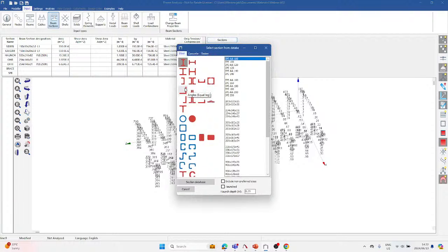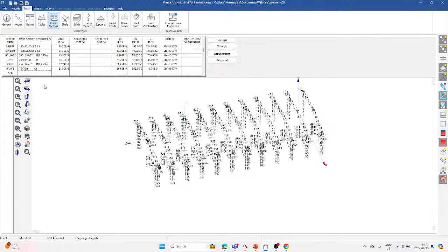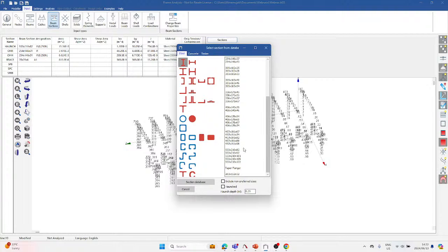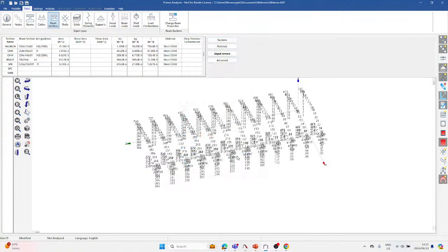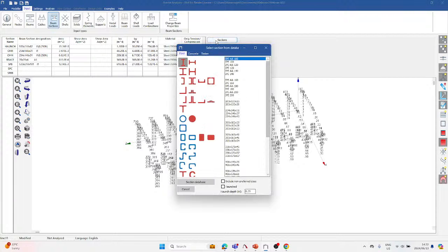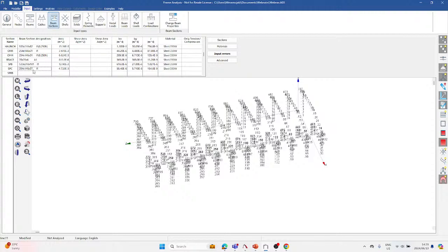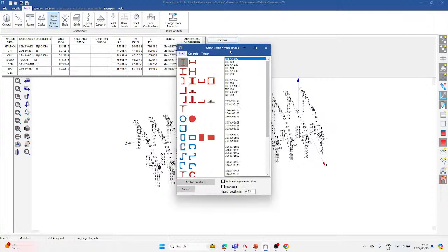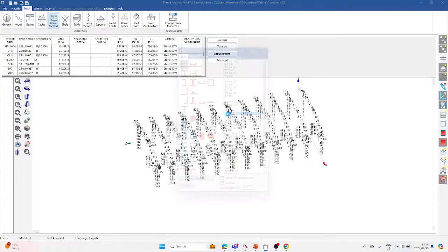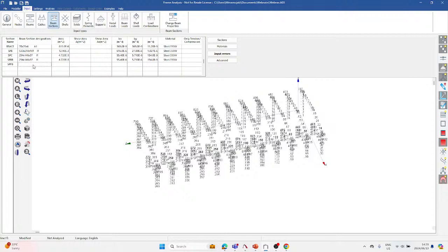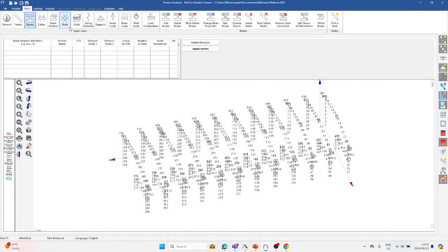And then for my brace, I'll have an equal leg, a 70 by 70 by 6, and then for my storage platform beam, I use 533 by 210 by 101, and then the column, I'll use the 254 by 146 by 37, as well as the back beam. And then the front beam, I'll choose a smaller section. Then I go to my beams so that I can start defining my beams.